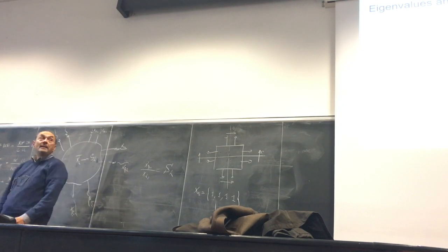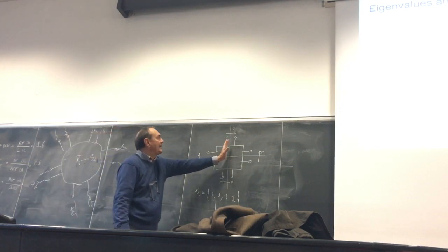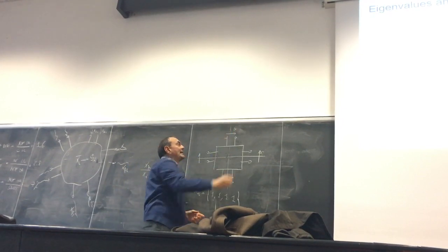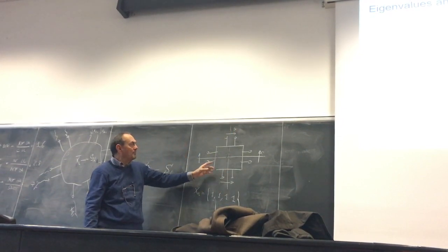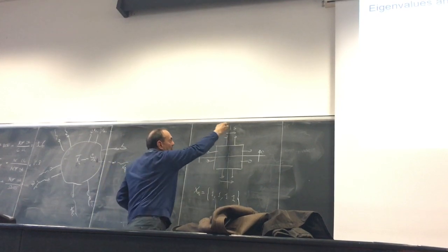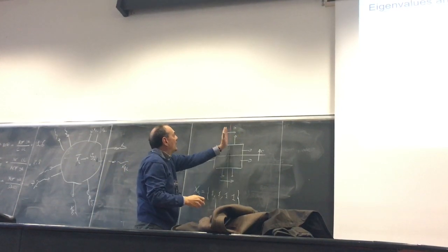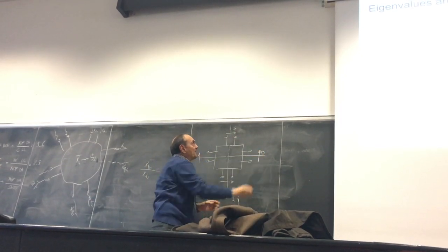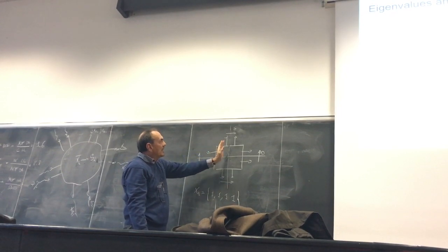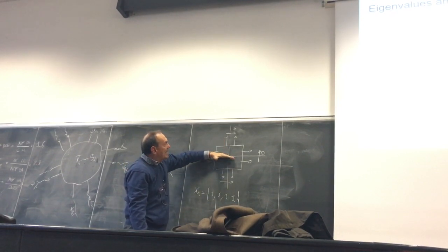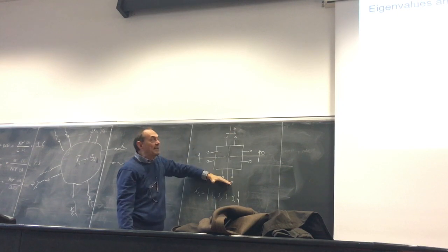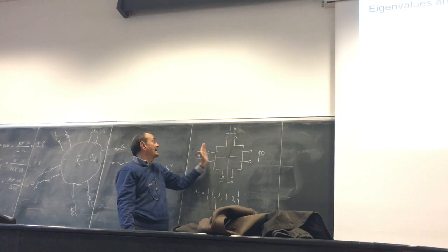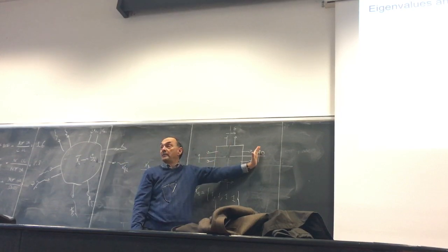Okay? Instead, if I have in this vertical plane not an open circuit, but a short circuit, what is different with respect to before? Let's suppose that here we have a short circuit in the middle of this plane, while this one remains an open circuit. So, if I have an open circuit here, the excitation here and here must be the same again. But if I have a short circuit here, the excitation here and here must be opposite.